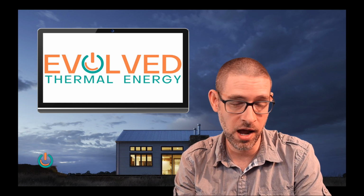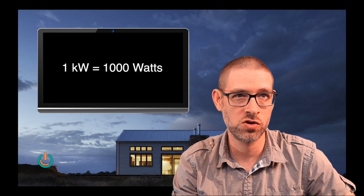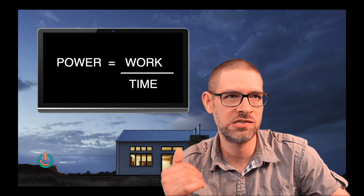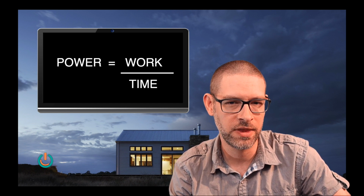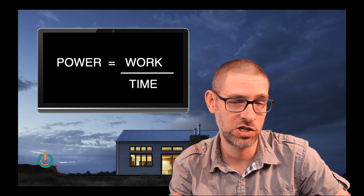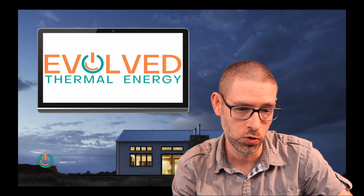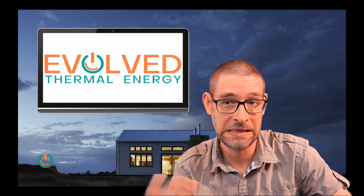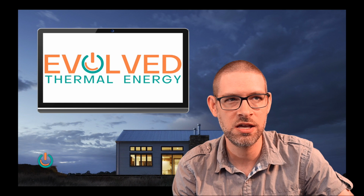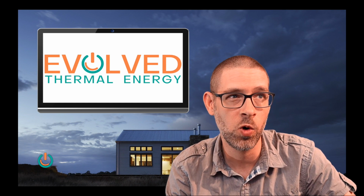Let's break it down to brass tacks. A kilowatt is 1,000 watts, and a watt, again, is a measure of power. Power is essentially how fast something is generating or using energy. Now, energy can't be generated from nothing, so generating could be better termed as converting from one form to another, i.e. with natural gas, we burn the fuel to get heat energy out of it. So power is how fast something is converting energy. It's a rate of energy transfer that would be equal to, in the case of a kilowatt, 1,000 watts.